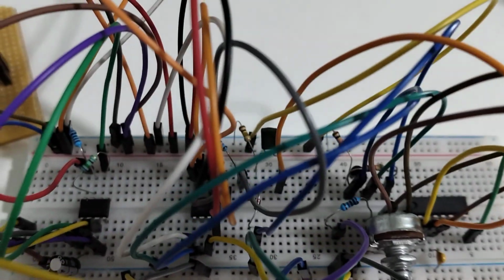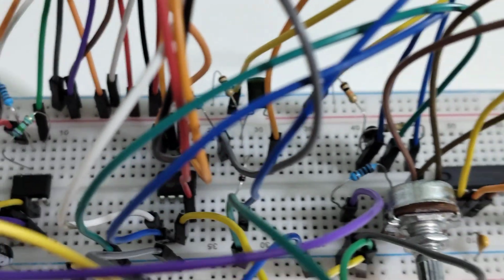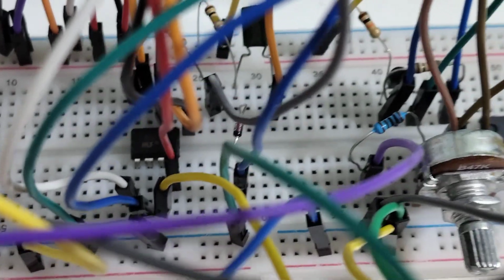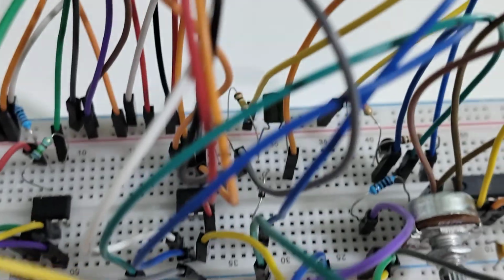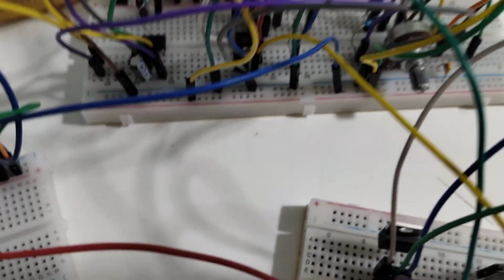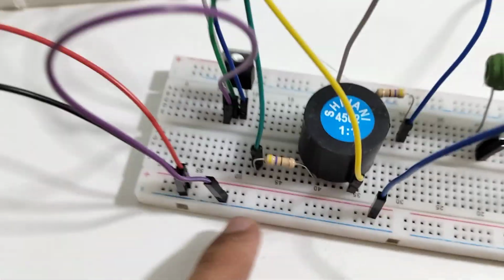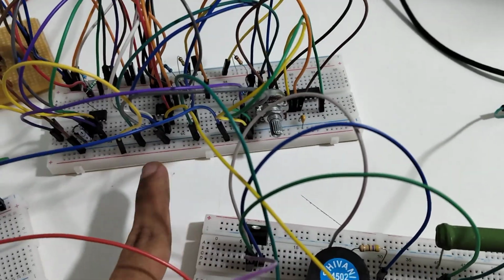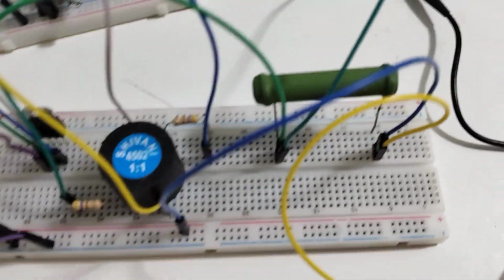And after that it goes here to the RC differentiator, that 1 nanofarad cap you see there. After the RC differentiator, it's going to go through the 4148 small signal diode, and it goes to the inverter, which is here, the BC547, and finally the monostable 555 over here. So the output of this is what I called the pulse in the schematic. That pulse is this yellow wire which is going on here to this third breadboard. So you can see the first breadboard is for the optocoupler, the second is for making the signal, and the third is for the power circuit, you could say.